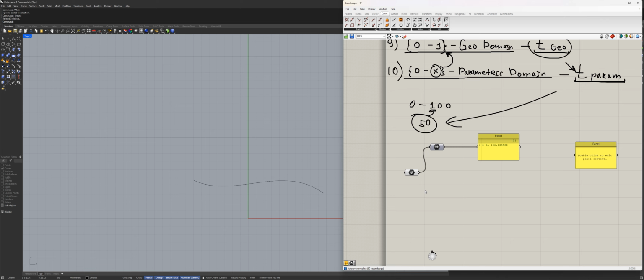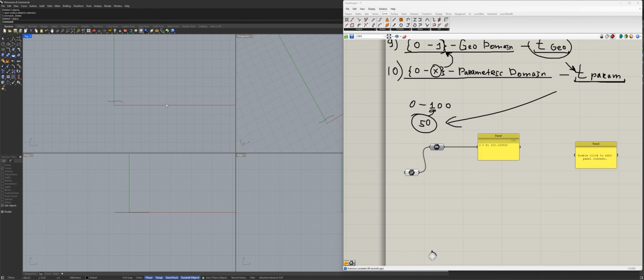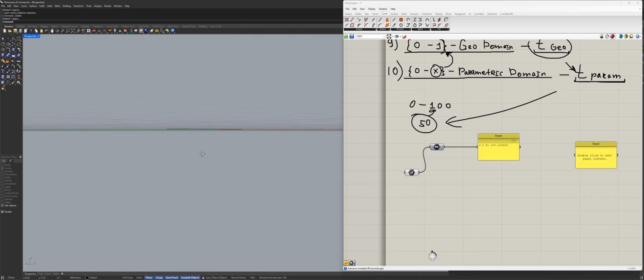Now we're going to look at the surfaces. Why did we start with the curves? Well, because surfaces can't be constructed without the curves. Curves are the basics. The curves are the base, and the surface is a consequence, and there are no exceptions. And if you tell me, well, Alex, I can go in, delete this old curve, and in perspective mode, there are a lot of tools which can construct a surface without curves, and what you're saying is wrong.